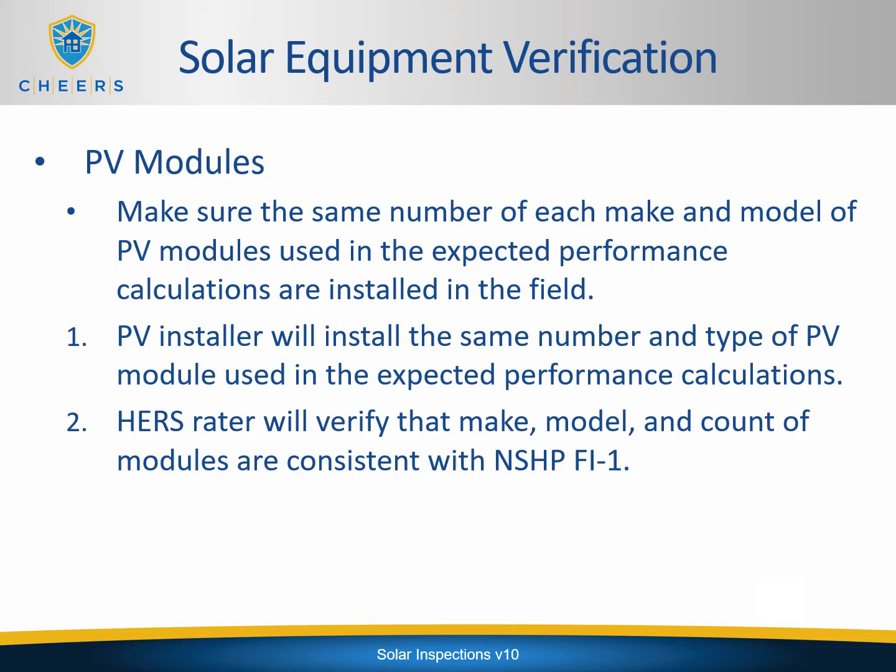Equipment verification of PV modules. You will need to make sure the same number of each make and model of PV modules used in the expected performance calculations are installed in the field. Now you will be able to count the number of modules easily, as you can see the separation between the different panels. However, to verify the make and model, you will need to get documentation from the installing contractor.